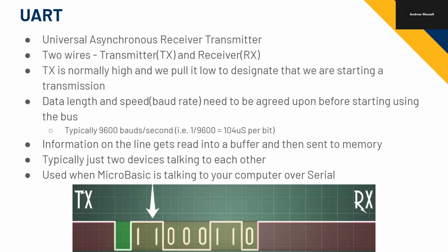Yeah, Alex. So it starts high. You do that with a system that goes high. Yeah, UART doesn't use pull-up resistors, it uses push-pull, which we'll go over at the end of this presentation. It's not a resistor, it's a switch.